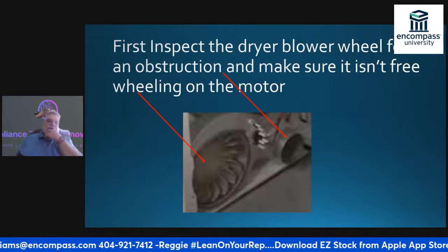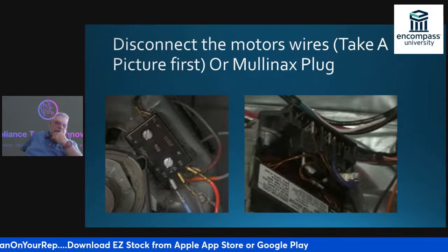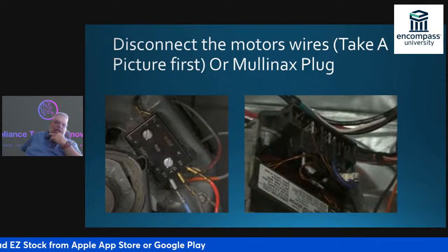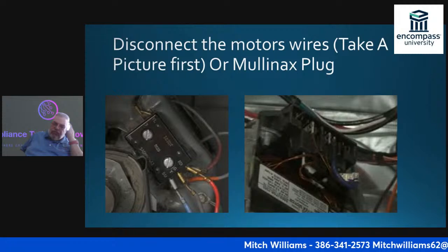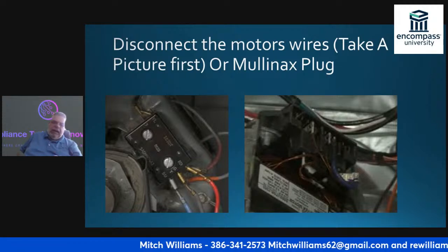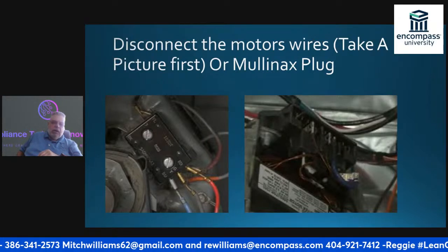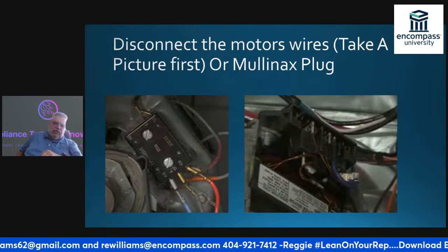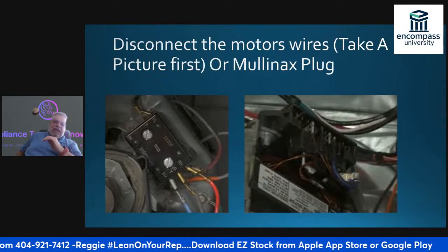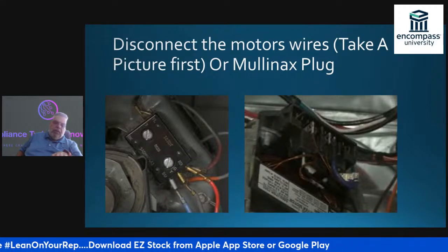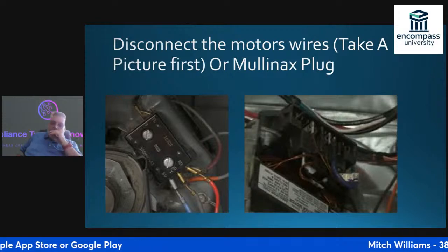Okay, so here's an example. I told you that there was a Molex plug, or these are the wires that actually connect to it. If I'm going to disconnect the motor wires, I'm going to take a picture of it. I am 64 years old. I have a pretty decent memory, but whenever I have something that has 6 or 8 wires, I'm going to take a picture so that I make sure I get every wire back where it belongs. This one only has 3 wires off the side that are bad.